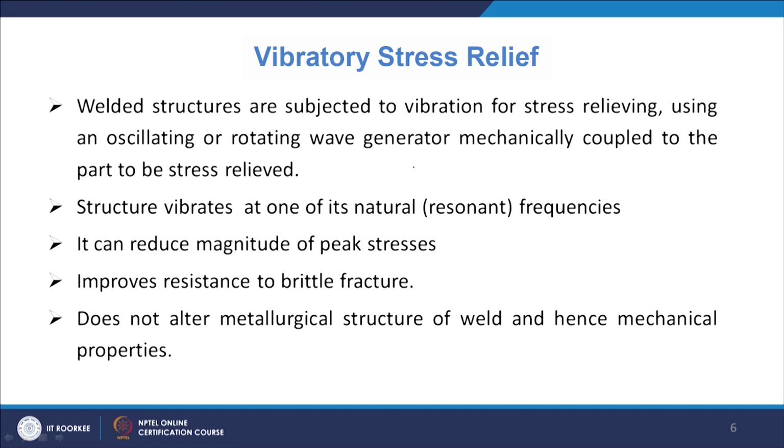What we do in this case, the welded structure is vibrated at its natural frequency, so plastic yielding occurs in the region of plastic deformation. In that region, that will serve the purpose of stress relieving.